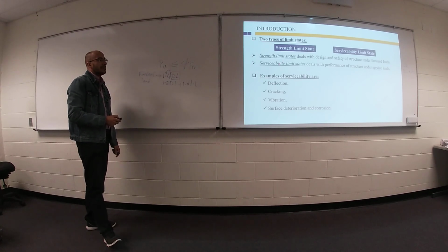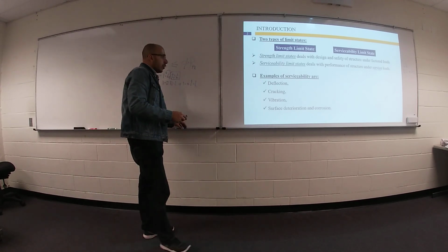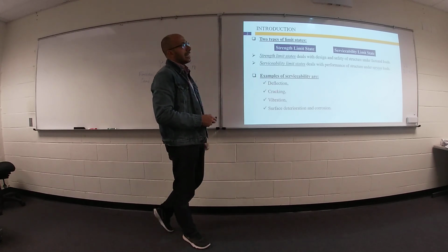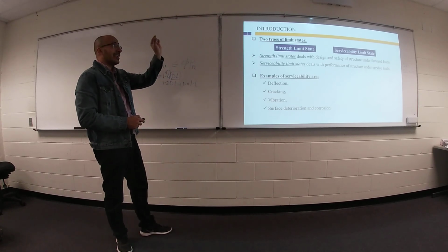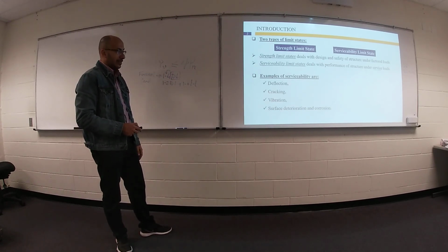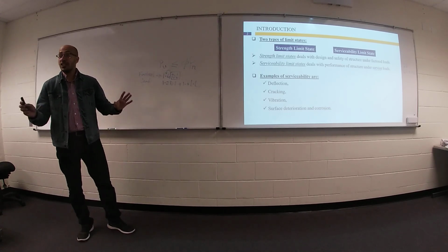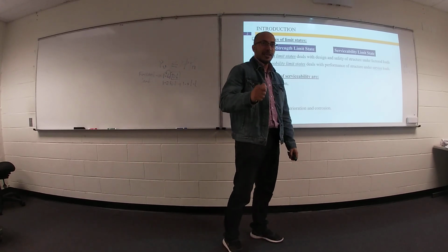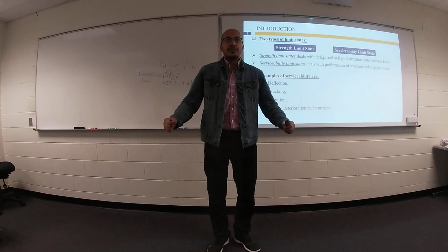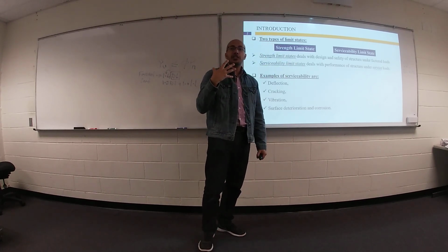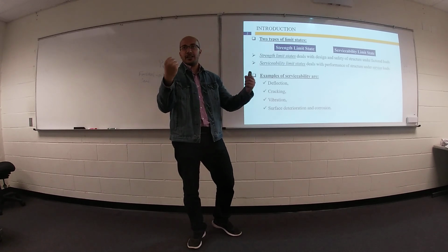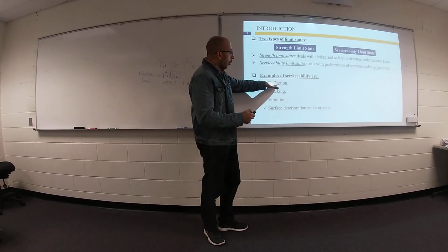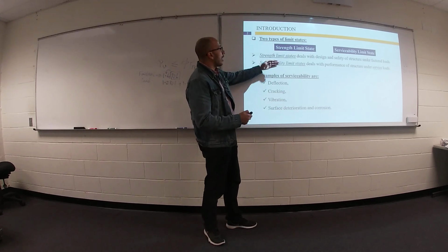What do you mean by serviceability? Examples of serviceability: we need to ensure your deflection of your structure is within the limit, your cracking in your structure is within the limit. Your vibration: sometimes your structure is safe, perfect, nothing wrong in your structure. But if you have a machine and you turn it on, something will happen in your structure. It's still safe, but you are feeling something wrong about vibration on the building. This is called serviceability. Remember, all of this stuff, I don't care about them regarding your design.